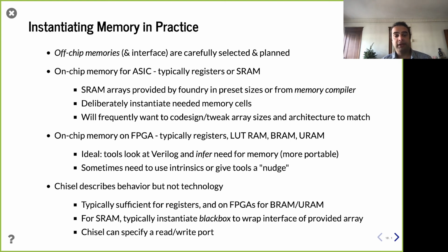For a given technology, making an SRAM array is a really big specialized thing. It's not as simple as a couple of logic gates tossed down. It's usually something called a memory compiler, which makes a memory for a given technology. So that's one option: use a memory compiler. Given the foundry, you can go ahead and make your own memories. Other times, the foundry, i.e. the manufacturer, is going to say, if you're using our technology, here are some preset memories we've already compiled. Consider using these, right?